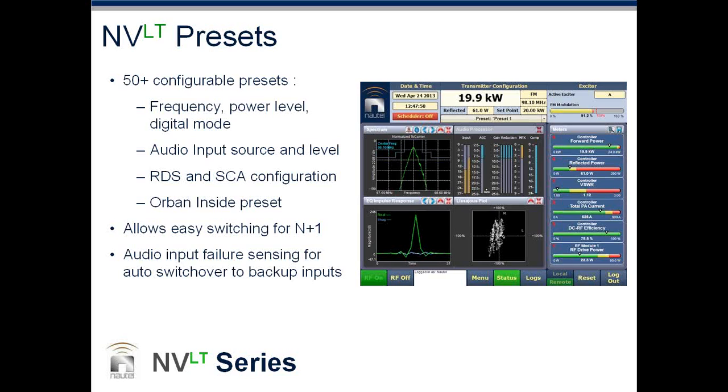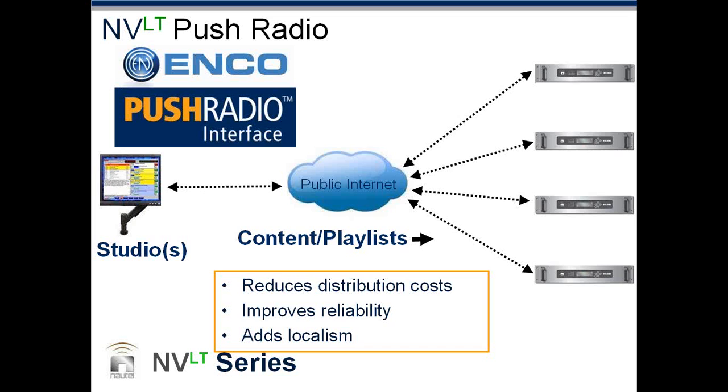Presets. This has been a feature in Nautel transmitters for a very, very long time. Right, so presets have essentially all the user-controlled variables: frequency, power level, the audio port that you're going to want to use, RDS and SCA configurations. And you can save, like it says there, 50 plus presets, and call them up for whatever operating mode or time of day or whatever the time calls for.